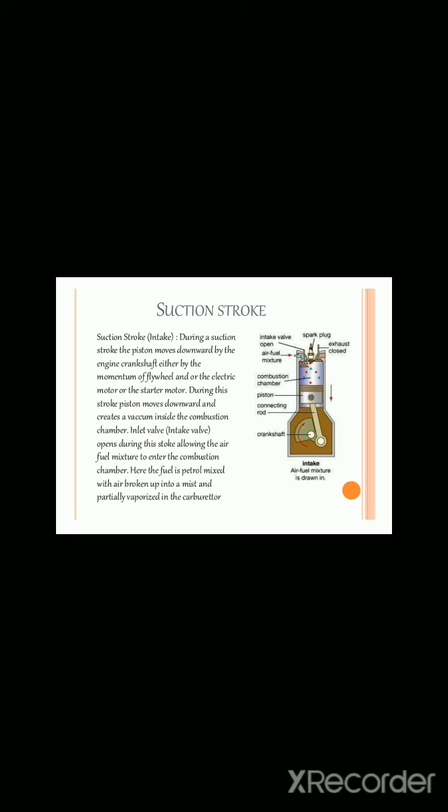The inlet valve, also called the intake valve, opens during this stroke, allowing the air-fuel mixture to enter the combustion chamber. Here, the fuel is petrol mixed with air, broken up into a mist and partially vaporized in the carburetor.